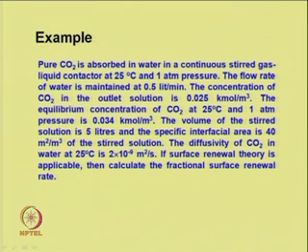The equilibrium concentration at 25 degrees C and 1 atmosphere pressure is 0.034 kilomole per meter cube. The volume of the stirred solution is 5 liter and the specific interfacial area is 40 meter square per meter cube of the stirred solution. The diffusivity of CO2 in water at 25 degree centigrade is 2 into 10 to the power minus 9 meter square per second. If the surface renewal theory is applicable, then calculate the fractional surface renewal rate.